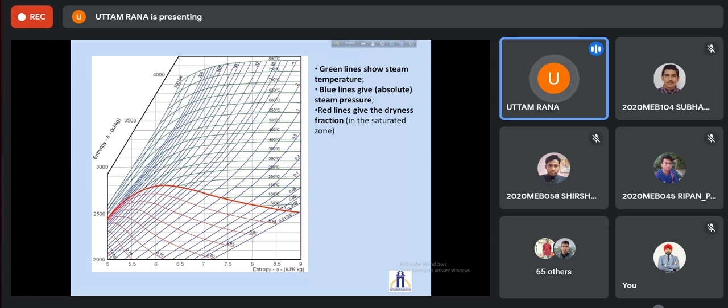Moreover, you will find there are different kinds of constant enthalpy processes. Throttling is a constant enthalpy process. During this process, let us say we take some state, steam at 250 degrees centigrade temperature, and the quality of the steam is, let us say, 0.95. So this is the point, and the corresponding pressure is 0.5 bar.